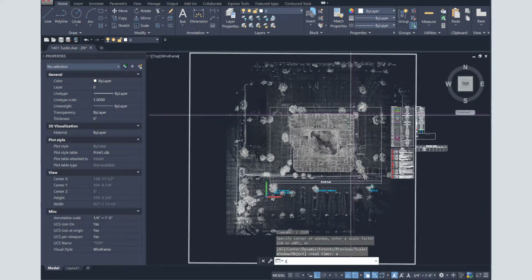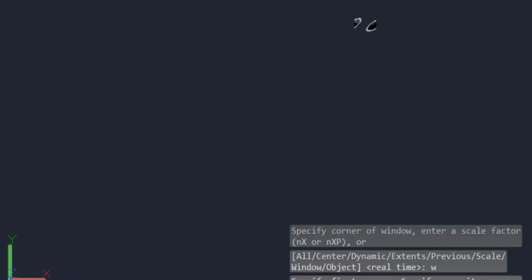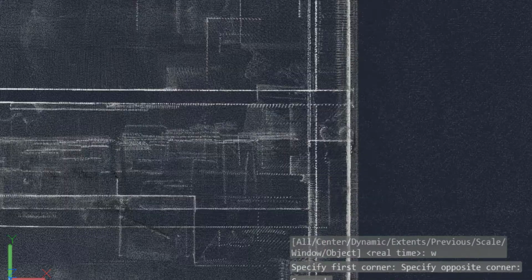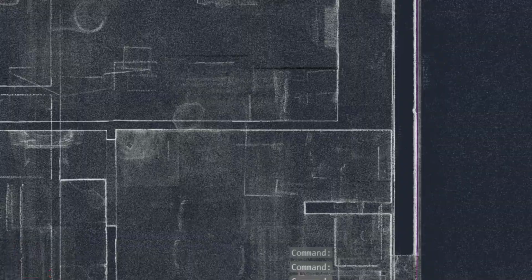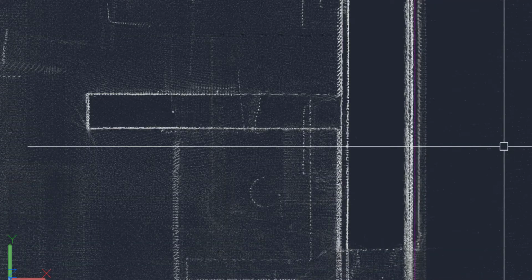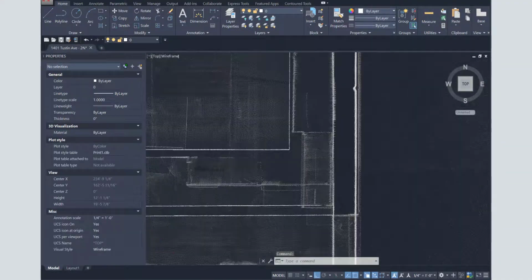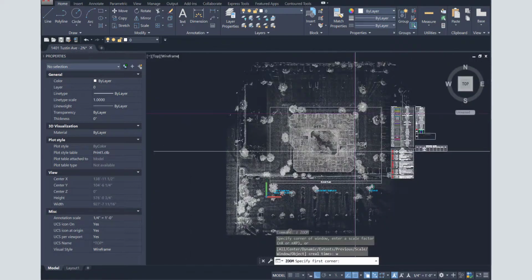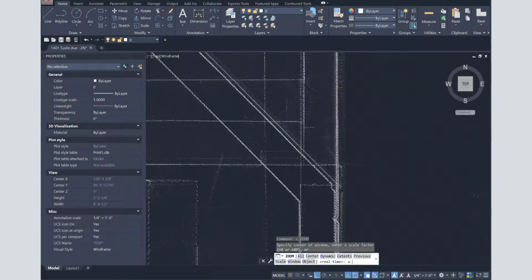Here you can see I've drawn an X-line from the bottom side, and at the top it isn't quite resting on my line. To determine if the building is angled slightly, or if it's just poor construction, I'll pan along this side and check to see where things go wrong. After checking the entire side of the building, I've determined that most of the wall rests along my line, and I can leave the rotation of the point cloud.